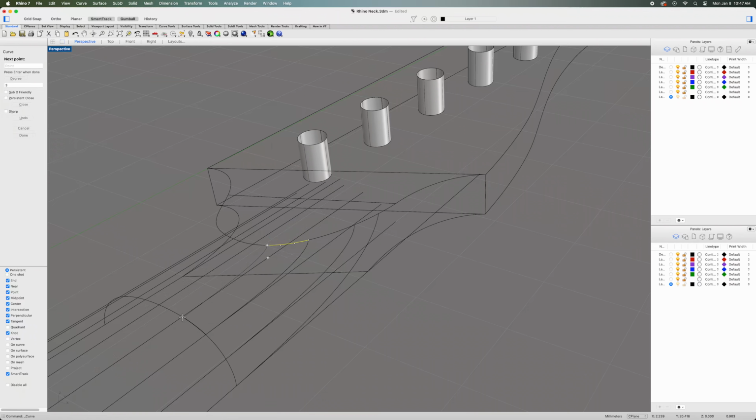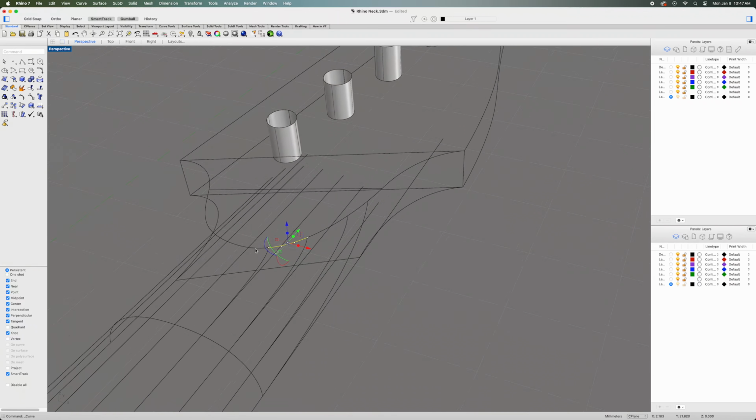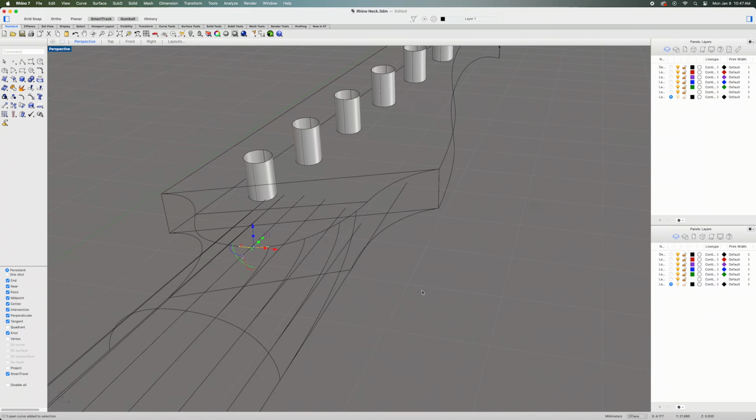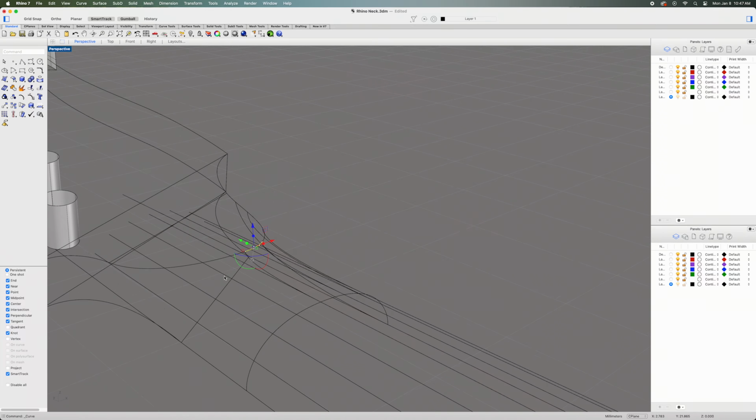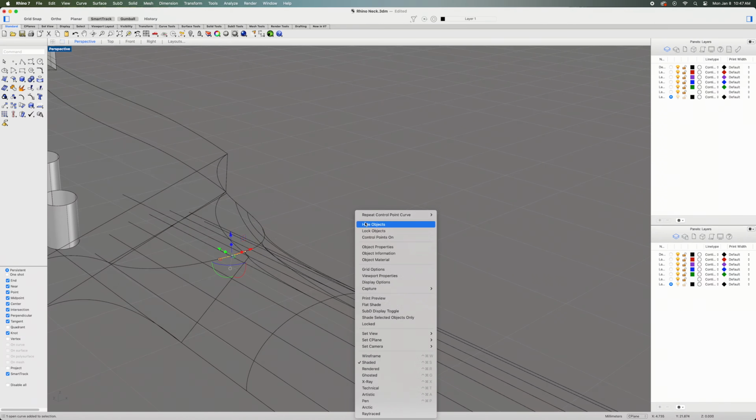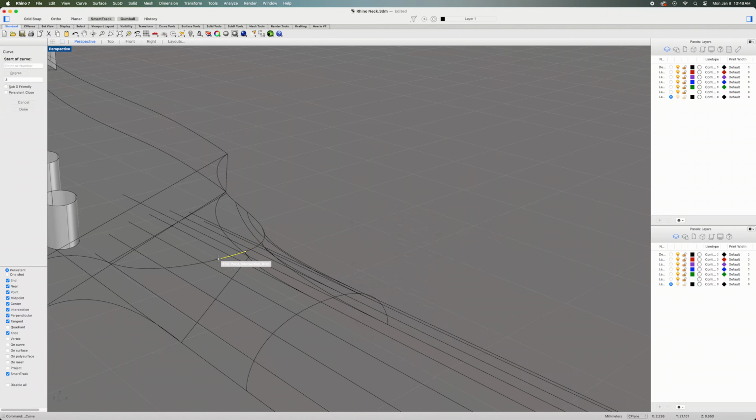And when it says perpendicular, I will click once, and then I will drag the line over to the start of that neck contour shape. And I know this probably looks confusing, but this is how I get a precise shape that I know I'm going to be able to apply a surface to that isn't going to have any issues.